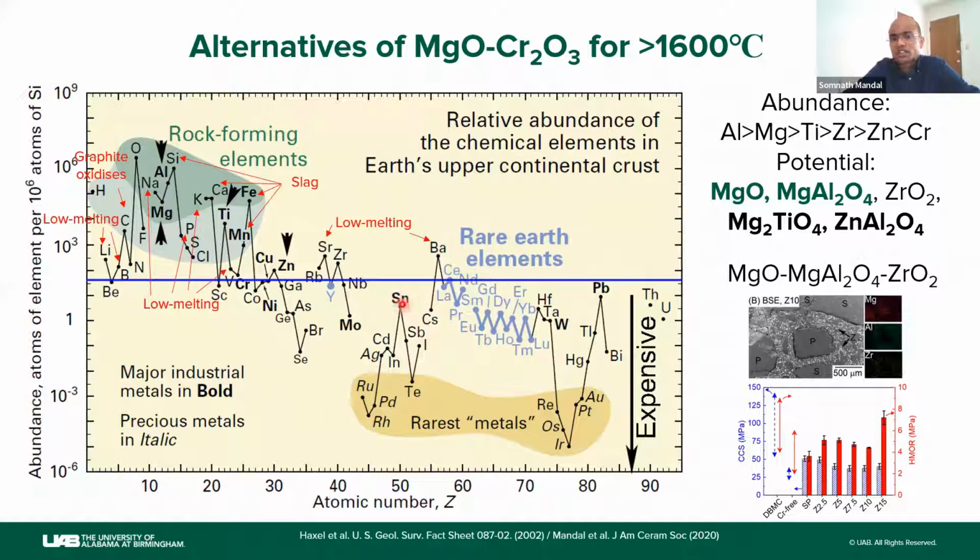There has been some work on magnesium titanate spinel, but it forms low melting phases, and it's also expensive. And then strontium, barium, they also form low melting phases, low melting oxides. There was one good thing, which is graphite. Even though magnesia carbon is used in steel ladles, in the RH degasser, where magnesia chrome is primarily used, oxygen blowing oxidizes this graphite phase and it causes degradation. So I was left with magnesia, alumina, titania, and zinc as the main chrome-free materials.